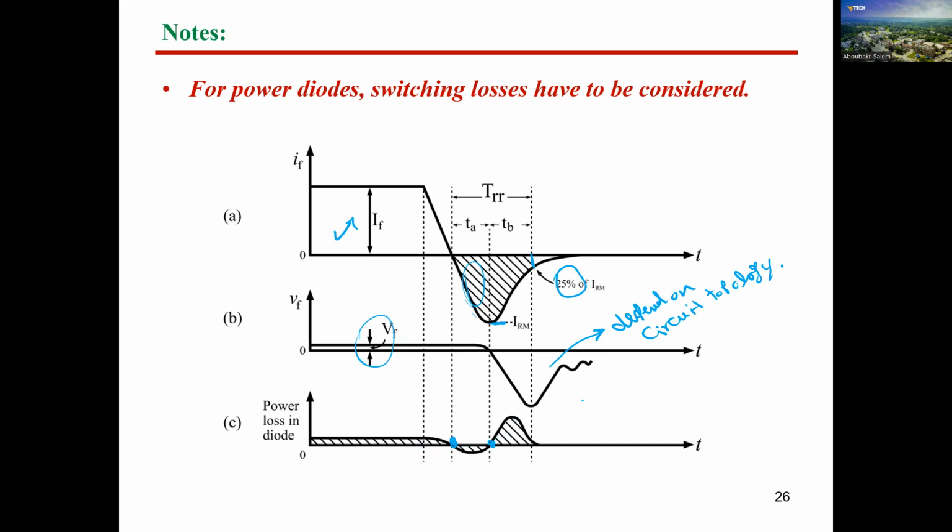So as you could see, guys, we don't have only conduction loss, we have also switching loss. Switching loss means we are making switching between this instant to that instant. And here you have a certain amount of power. So can you see here? All of this power is called switching power or switching loss. So this should be considered also for any power electronics element or any electronic element. Okay. Nice.